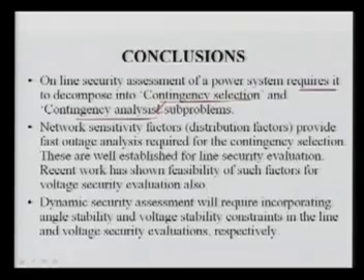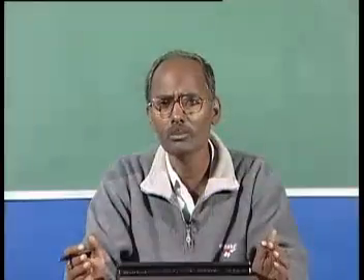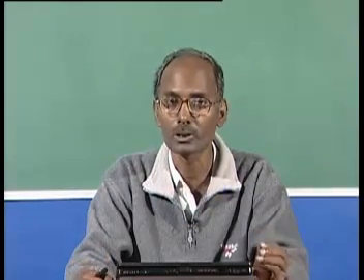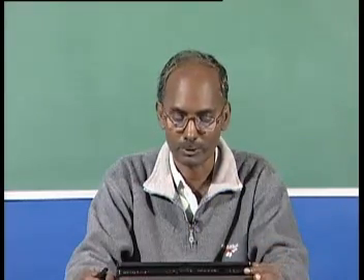These are well established for line security evaluation. Recent work has shown the feasibility of such factors for voltage security as well. Earlier, these distribution factors were very widely used for line security analysis, or you can say megawatt security evaluation, but nowadays they are also used for voltage security evaluation. I did not discuss how these distribution factor methods are used for voltage security evaluation, because there are so many distribution factor methods proposed in the literature. So it is not possible to do that, but you should know that these distribution factors are very widely used for both line as well as voltage security evaluation purposes.